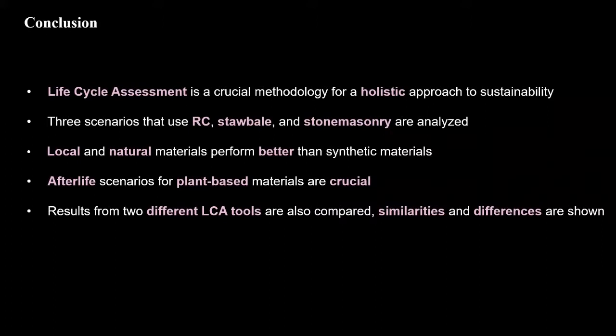To conclude, we can say that life cycle assessment is a crucial methodology for a holistic approach to sustainability. In this study, the comparison of the LCA of three different structures is executed. One of these structures is reinforced concrete, the others are structures made with natural and local materials, which are straw bale and natural stone. The results show local and natural materials perform better than synthetic materials that are transported from different locations. It is also discussed that afterlife scenarios are crucial for plant-based materials.